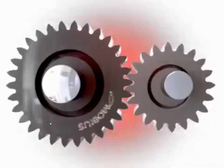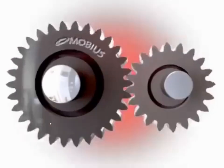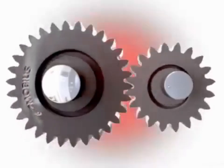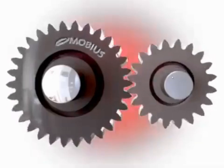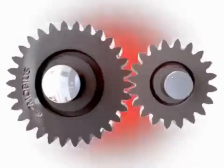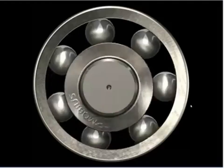As the gears mesh together, ideally that force would be uniform, but if you look closely at the animation, you can see that this is actually eccentric, or it could be bent. So the force in that mesh gets stronger and weaker, stronger and weaker. And we can see that in a time waveform as well. Those pulsations you can see occur as the teeth go into a stronger mesh and a weaker mesh and a stronger mesh. So it really complements what the analyst can do with the spectrum alone.